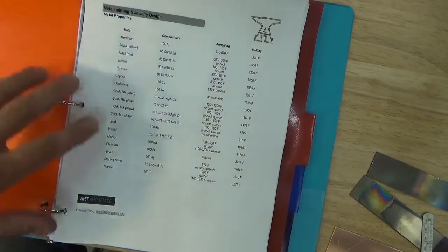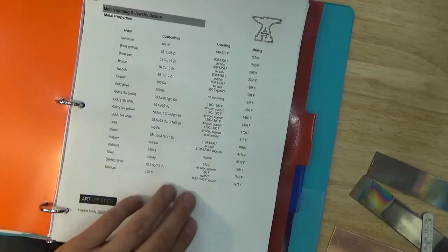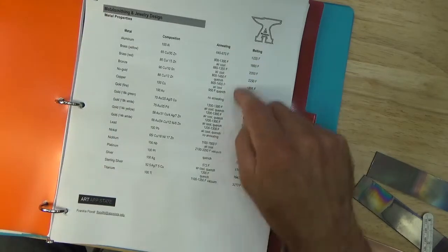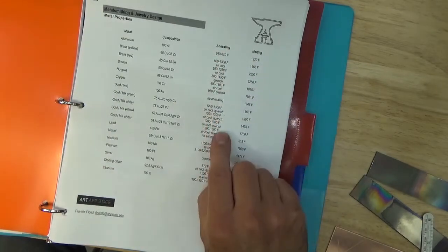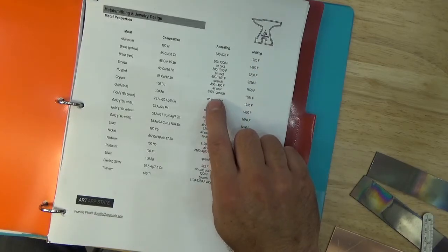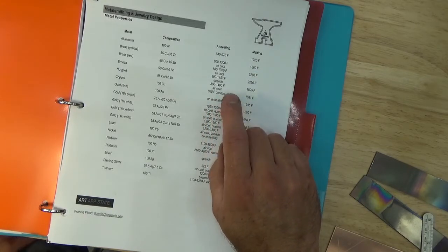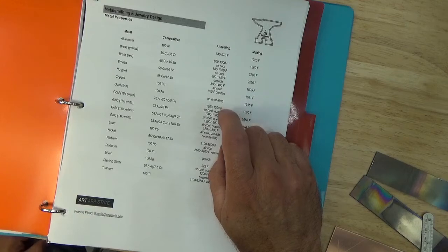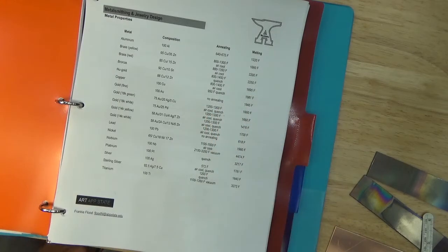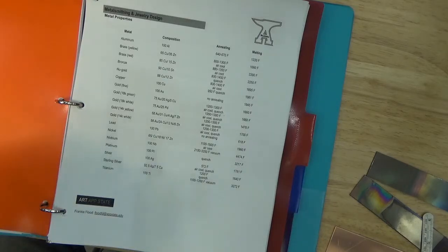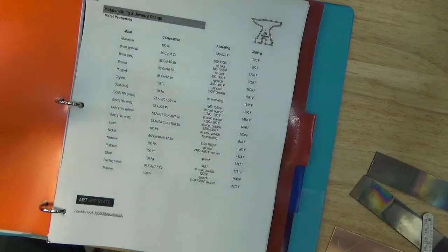All right, one thing to mention about our metal properties handout is you'll notice that in the annealing column, it not only has the annealing temperature, but it also has whether the object should be quenched or air cooled. And quenching just refers to dunking the metal into a container of water